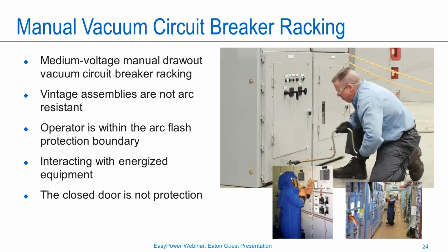I mentioned here, it says the closed door is not a protection, again, because vintage assemblies have not been tested to arc resistance standards. And so because there is no such test data, we don't really know what's going to happen with the door if there's an arc event.